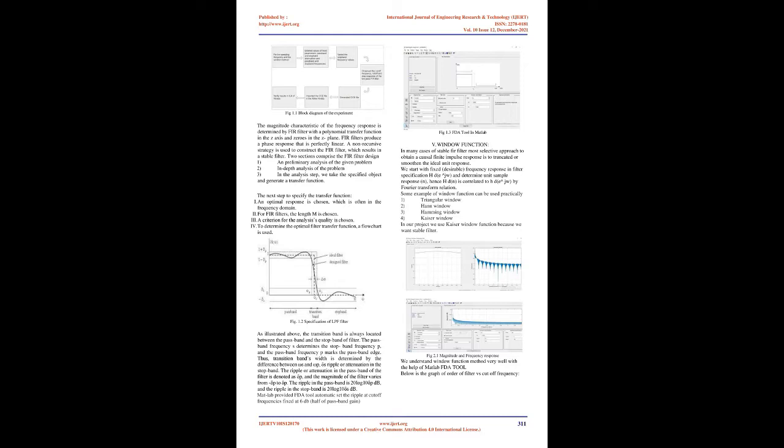The magnitude characteristic of the frequency response is determined by the FIR filter with a polynomial transfer function in the z-plane and zeros in the z-plane. FIR filters produce a phase response that is perfectly linear. A non-recursive strategy is used to construct the FIR filter, which results in a stable filter.